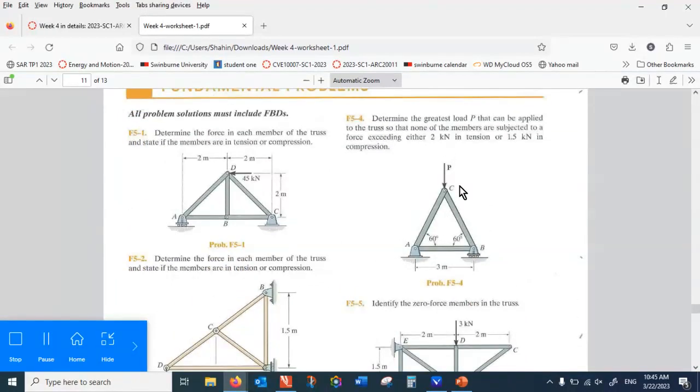We discussed that in truss structures, it is common to have redundant members. Redundant members are also called zero force members. Anyone remembers what a zero force member is? Shah, can you tell us what is a zero force member, redundant member? If two forces are like... forgot the name, two like joined with another one. So you're talking about the rules, about the condition, but the definition is for a given loading, maybe some members are not needed. If you remove them, they won't change anything. So they only make the problem simpler.